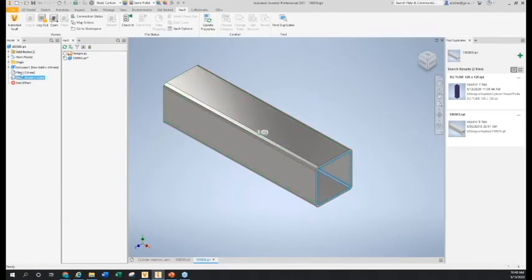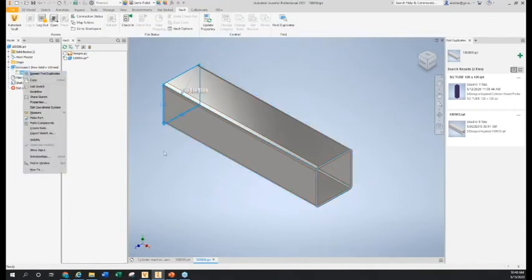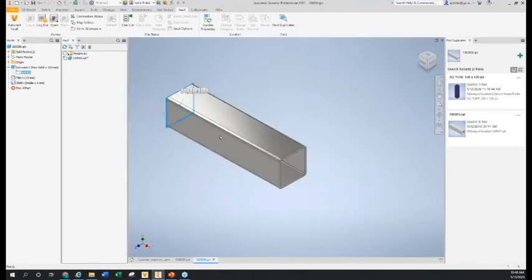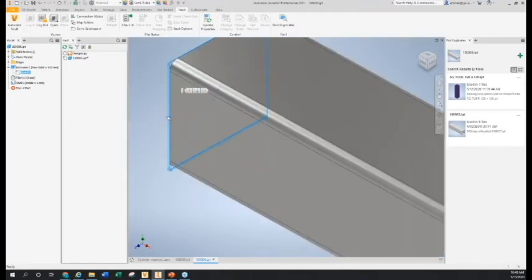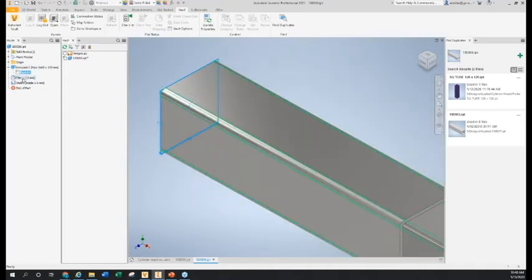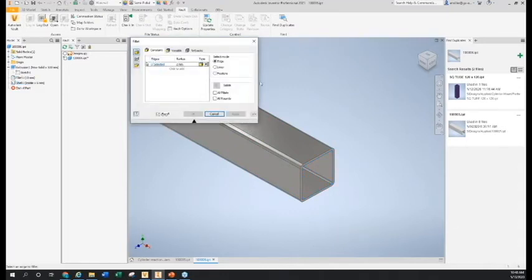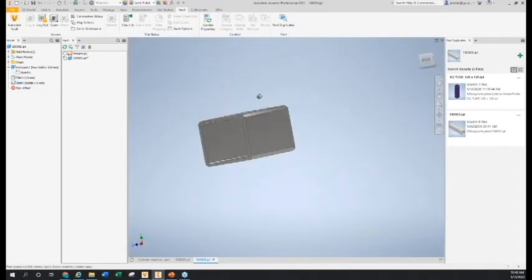This one was created using just a square tube. If I look at the sketch here, you can see that, unlike the other parts, where it was extruded bidirectional, this one's in one direction. So there we've got 120 by 120 just square, but then they created the fillet on the outside here, and then just did a shell on it. So obviously a pretty weird way to create a tube like this.